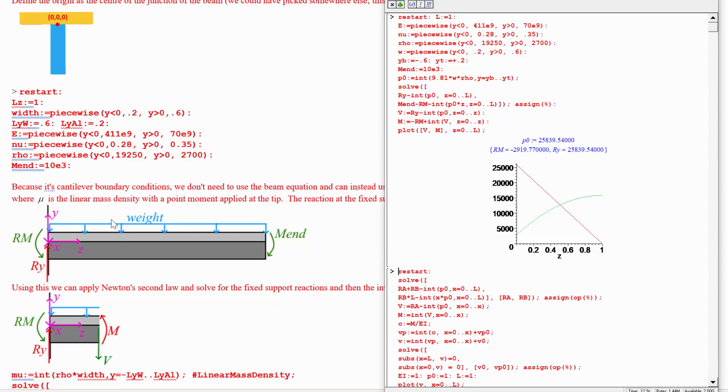And that means that we have to have no internal shear force at the end of the beam, and that means the moment stops changing there and should end up at exactly the right value to jump down from this applied moment at the end, which was 10e3, but that doesn't quite look right. It looks like we've ended up at about 15e3. So something seems amiss here by what we calculated for the internal bending moment.